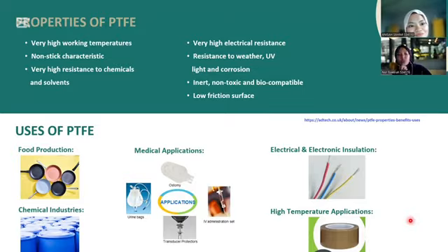So we move on to the properties of polytetrafluoroethylene, where the property is very high working temperature, as PTFE can operate at temperature up to around 260 degrees without breaking down, making it ideal for high temperature application. It also has non-stick characteristic because of its extremely low coefficient of friction.